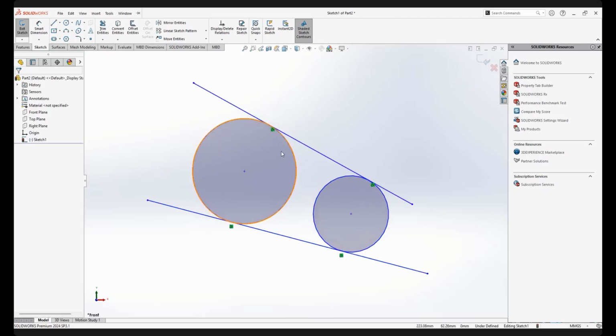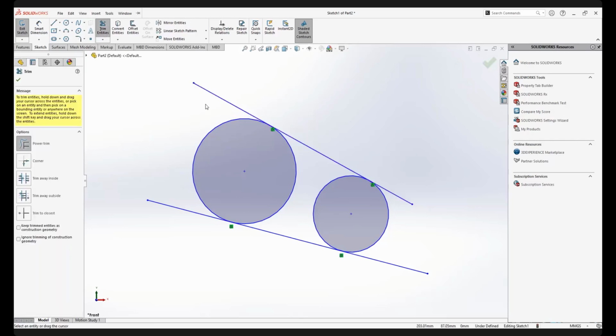do some shaping. Okay, I have not yet mentioned in class, when you have something like this, you already put the dimension. This one I just show you freely. We have a trim here. Can you see trim? Trim, we can cut out any portion that we want to remove. So you go for trim. So just bring like this, like that, like that.